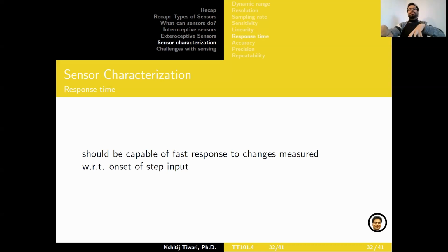And typically this is measured with respect to, let's say, if you're from an electronics background, you would know these step signals, right? Or PWMs, if you're seeing the square waves, where you have a zero which is considered an off state, and then there is a step, after which it's considered an on state. So when you have applied one step as an increment in the input, how much time does it take to at least reach 90% of the response to that step on the output side? That's your response time.